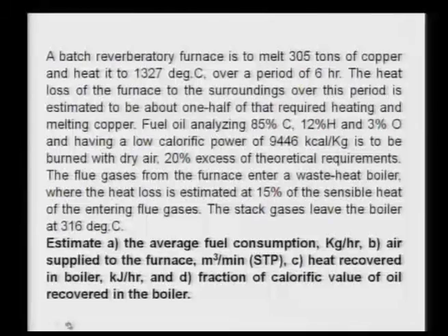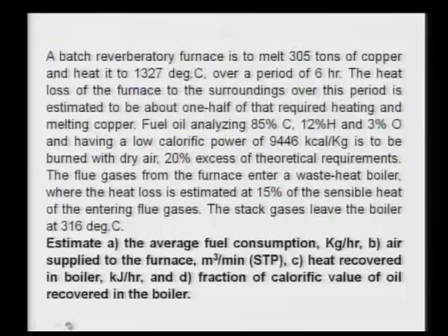Problem number 2, a batch reverberatory furnace is to melt 305 tons of copper, a typical problem on melting, and heat it to 1327 degrees Celsius. Now, recall here the temperature is 1327 degrees Celsius over a period of 6 hours. The heat loss of the furnace to the surrounding over this period is estimated to be about 1/2 of that required for heating and melting copper.